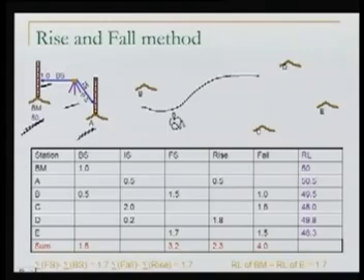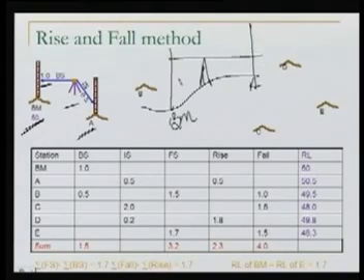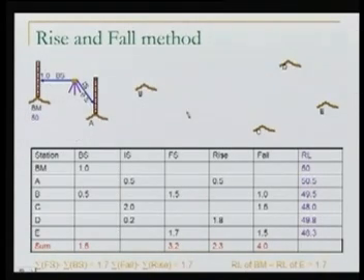If our benchmark is here and over here is A, this is where our instrument is. I'm taking the observations like this. So this is 1 meter, this total, and this is only half a meter. So obviously A is higher than benchmark. So this is how now I know that A is higher. So A has a rise of 0.5.